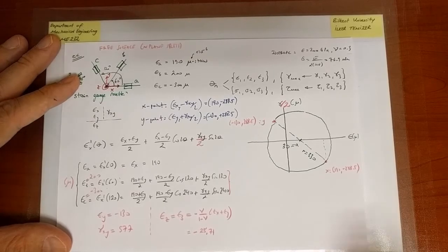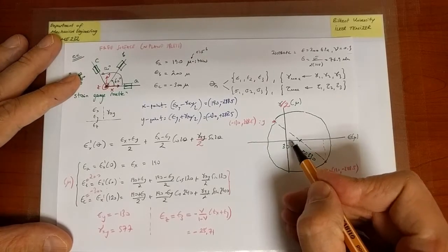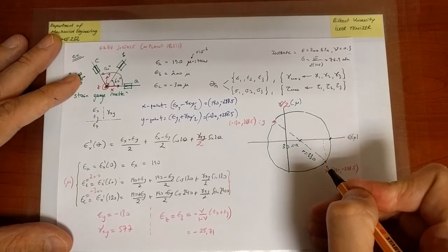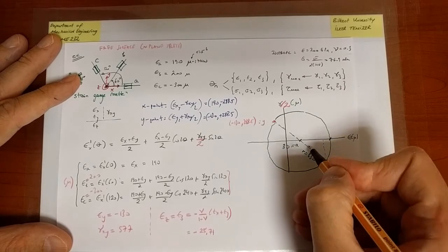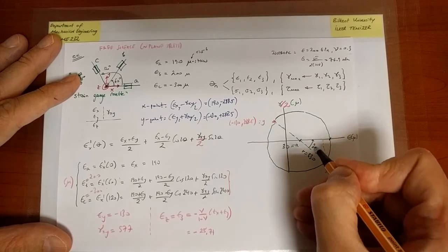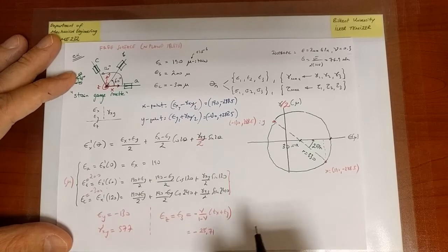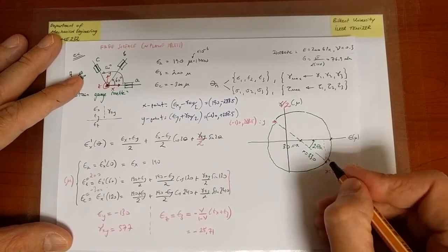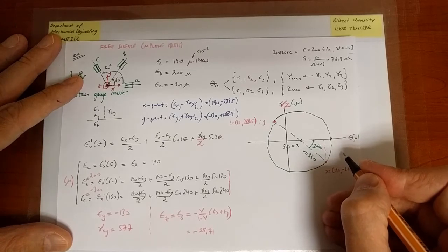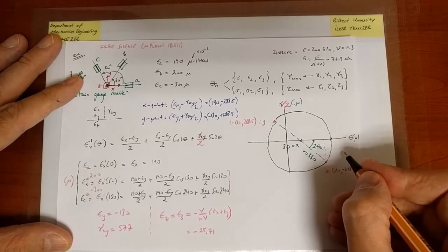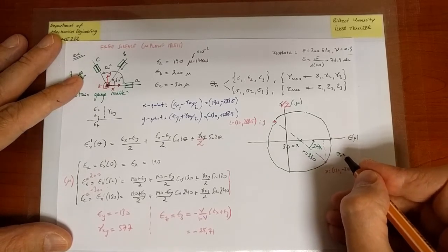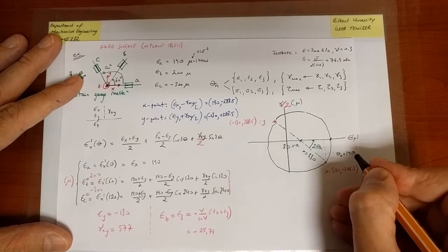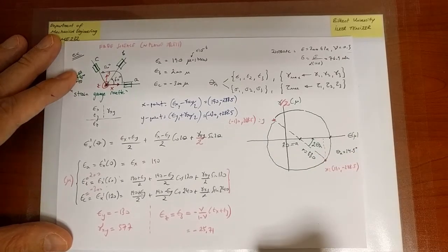Okay, so that is going to send me from here to a, first of all, x will rotate through an angle 2 theta n on the Mohr circle, theta n in the physical space. You can easily calculate, in this case, 2 theta n to be 29 approximately, or theta n to be roughly 14.5 degrees.